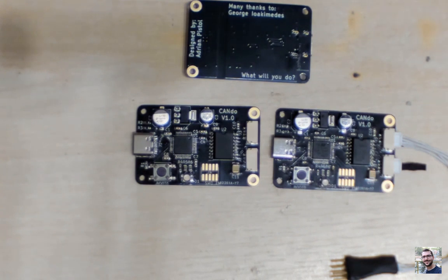So the STM has a built-in USB bootloader, I think, right? So that's how you flash it over DFU. It does. Nice. So you don't need an ST-Link or anything. Yeah, but I got a header for it, so if I ever need to, I can. And it's version 1.0, so first try and it works. Yeah, really. The main reason it worked so well was because I ported firmware instead of writing my own. Right. And I just did some very rudimentary changes because it already was quite configurable.